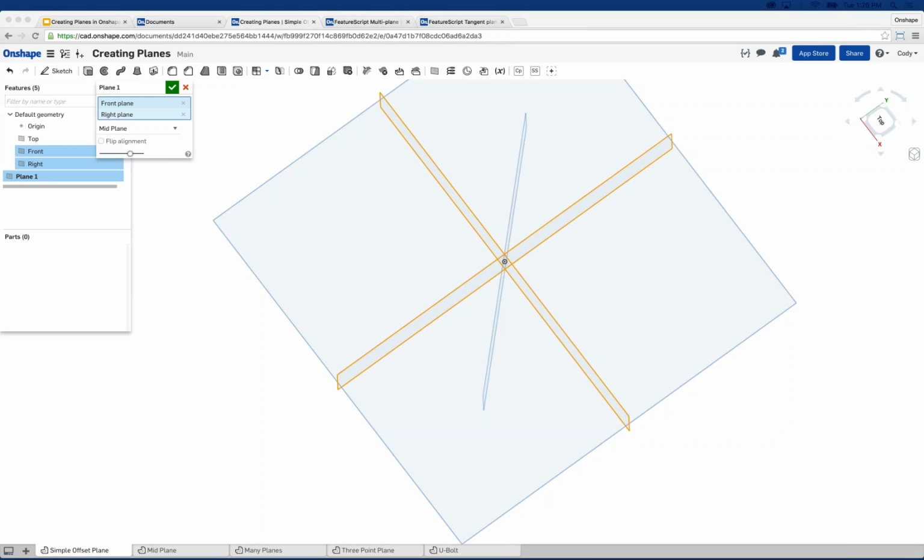Now on that 45-degree plane, can you also move it forward or backwards to translate? You can also insert an offset from that, and that's an important point. You can construct this plane and then construct another plane off of that as a reference. So it's entirely up to you. You could also construct geometry out where you wanted the offset to be and then drive that as well.